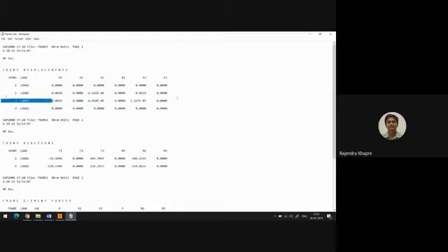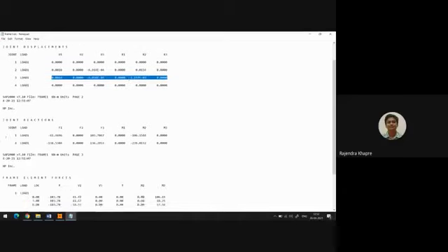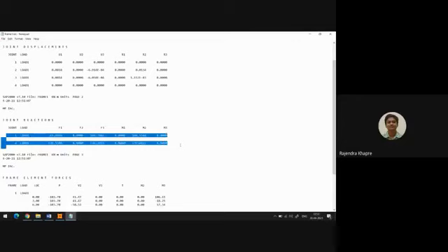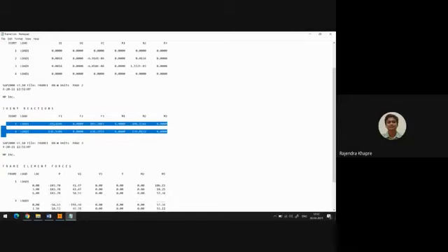Similarly, this is the third joint. The third joint is also showing a displacement in X direction, and in Z direction, and there is a minor value of rotation also. As far as joint reaction is concerned, we have already seen there are two joints, joint 1 and joint 4. So the values are there on the screen as well as in the output file.